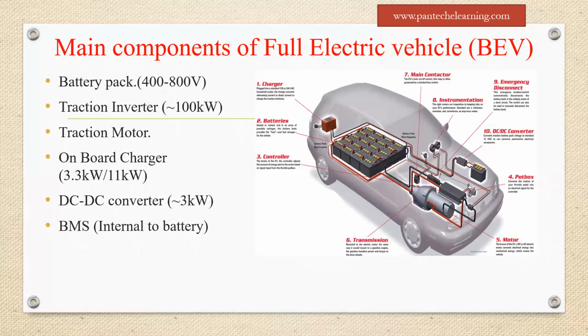So the range the client gives, they need 3.3 kilowatt or 11 kilowatt for the battery. And the DC converter, 3 kilowatt of DC converter we need for this particular battery type of electric vehicle. And for this, you need to develop the control system also.